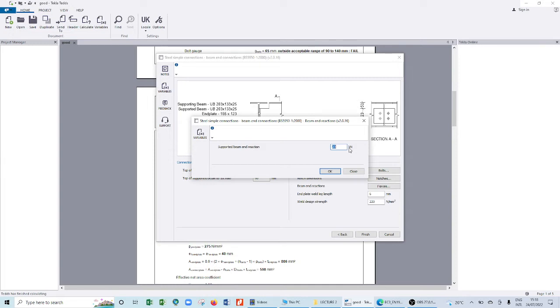Multiplied by gravity, because weight is mass times gravity, I convert it into newtons. Divided by 1000, I convert it to kilonewton. So now I have these two: 0.75 plus 14.4. What do you get? 15.21 kilonewton. This is the GK.